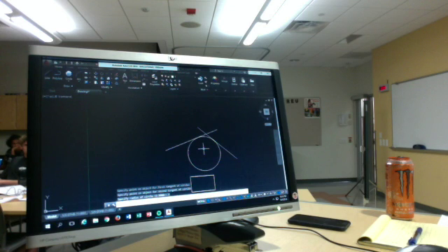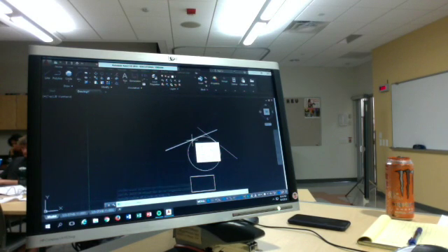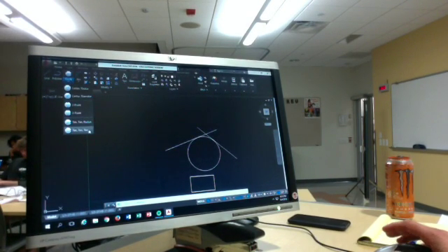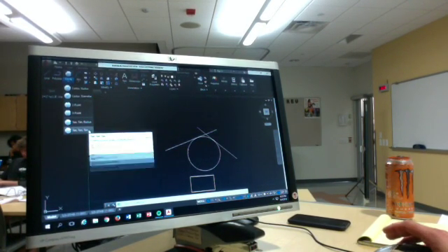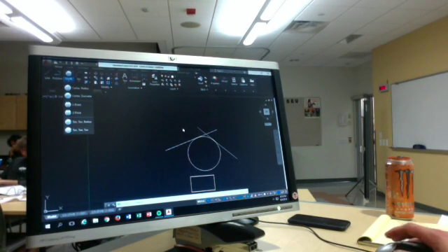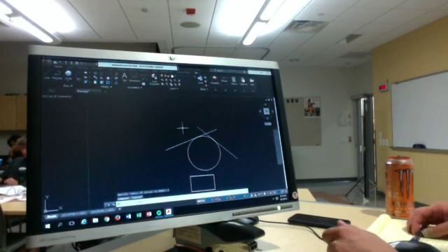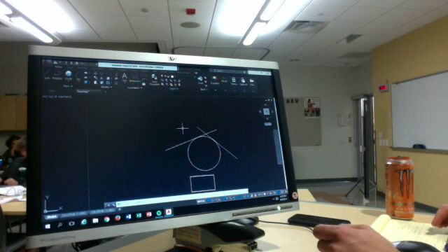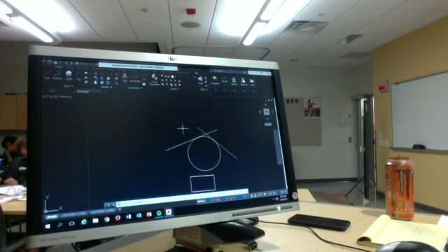We'll get into trim commands later, but basically, you're putting a fillet on an edge. That's all that you're really doing with a tangent, tangent, radius. And then they also have tangent, tangent, tangent. It's exactly what it sounds like. You choose 3 points, three lines. Circles are oddly difficult to choose from. Any questions on circles before I go on? Cool.